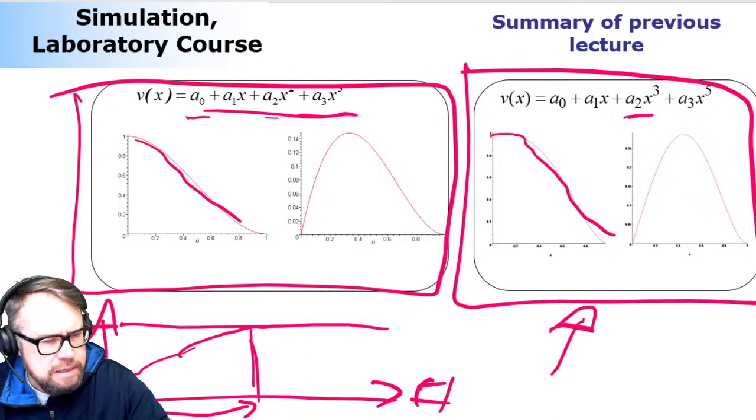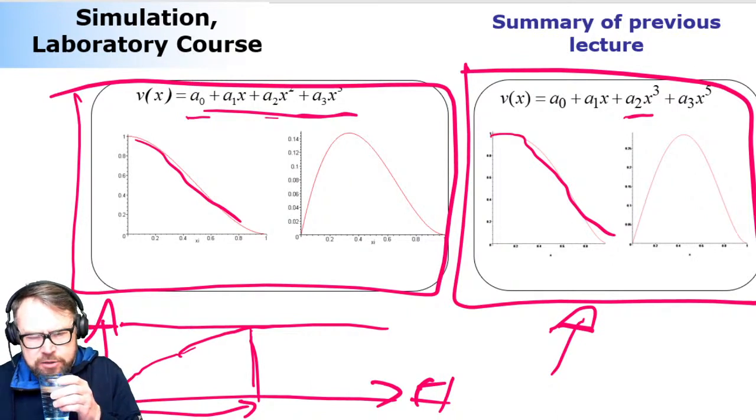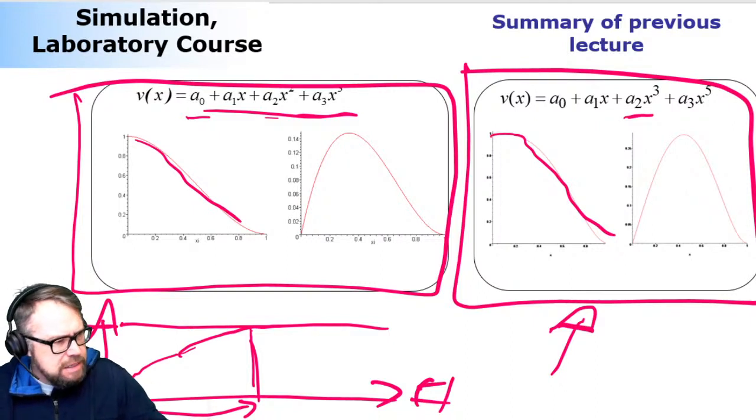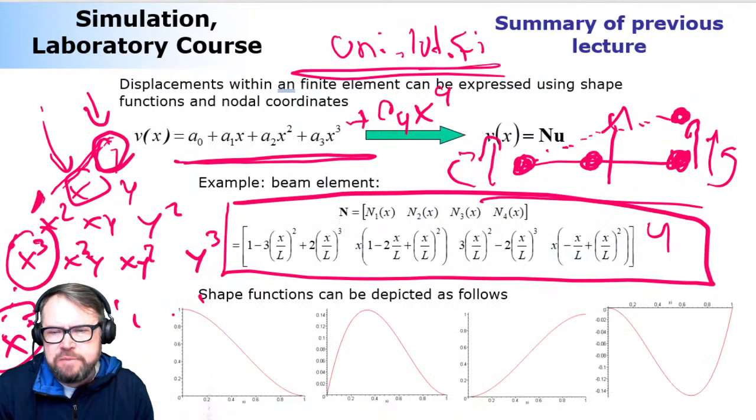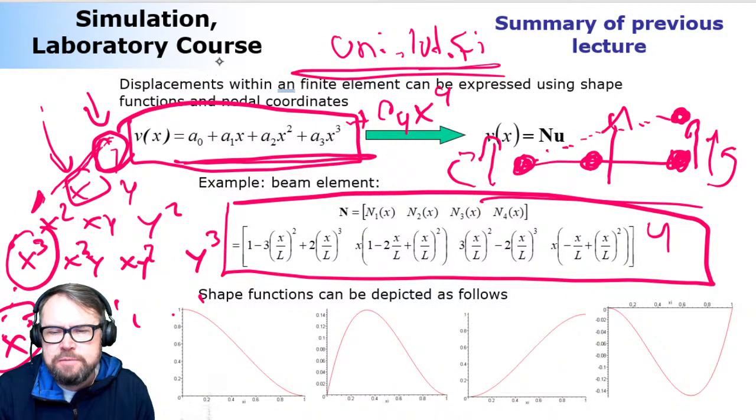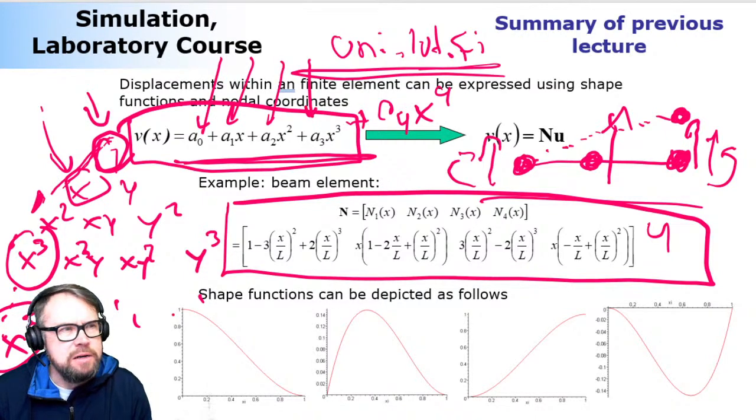And that's simply because if the convergence rate is good, it means that your computational efficiency will be enhanced. It will be better. Okay, so the polynomials tell you, and then the one thing that I forgot to mention here is that what we do here with polynomials is that we want to re-express the unknowns of the polynomial by nodal degrees of freedom. And once you do that, then you get this shape function matrix.